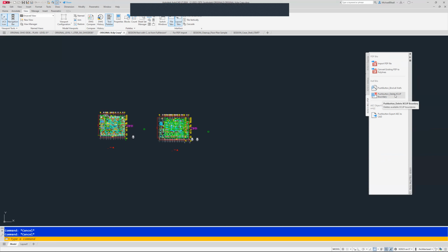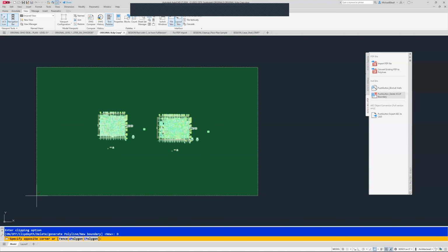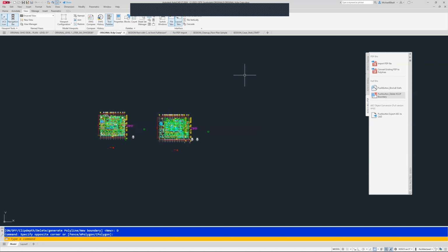It does a delete and it says select objects, and I put ALL in the button. So I'm just going to click the button and it's over. Prove it. Okie dokie. That's it. Nothing's there. So if life hands you one where you go to do a crossing window and all these little boxy things pop up, hop on over here to the button.